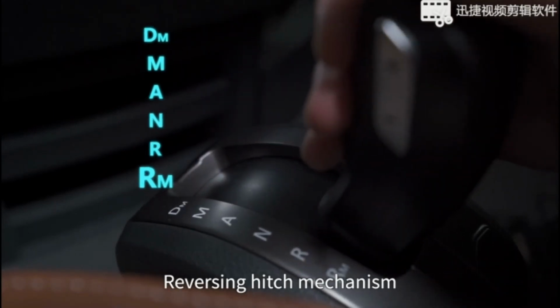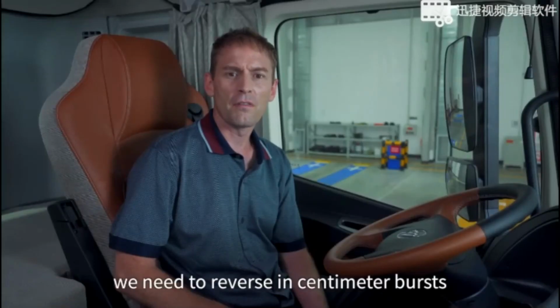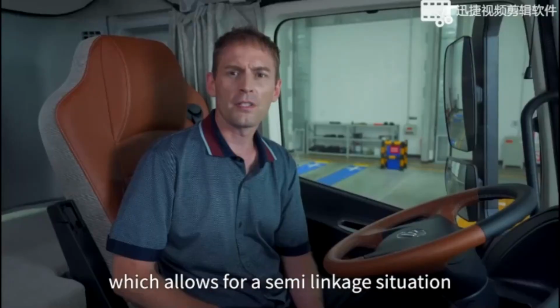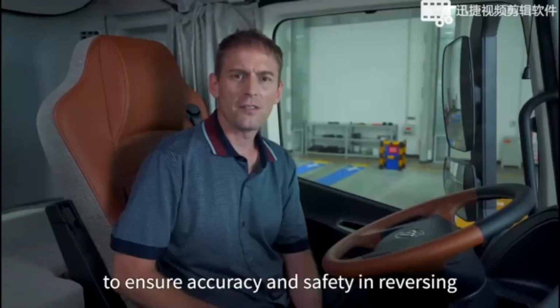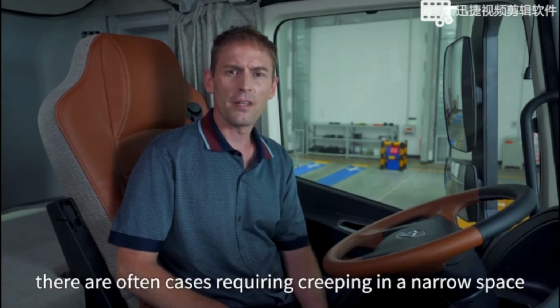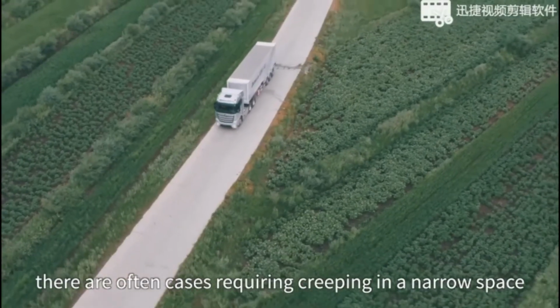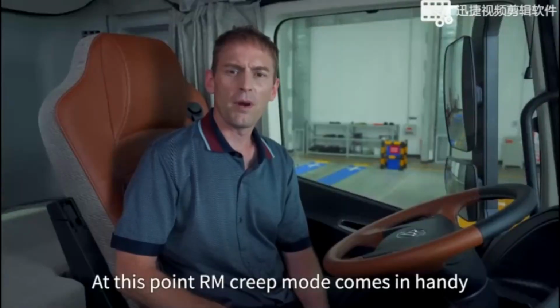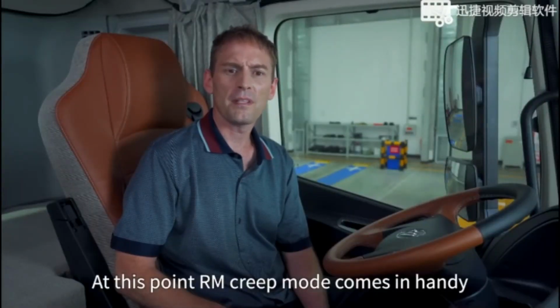Reversing hitch mechanism. During hitching, we need to reverse in centimeter bursts. This is done with the RM gear, which allows for a semi-linkage situation, further reducing speed to ensure accuracy and safety in reversing. In daily use, there are often cases requiring creeping in a narrow space and requiring high accuracy. At this point, RM creep mode comes in handy.